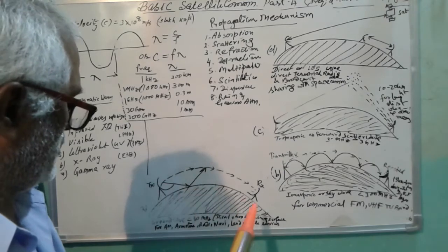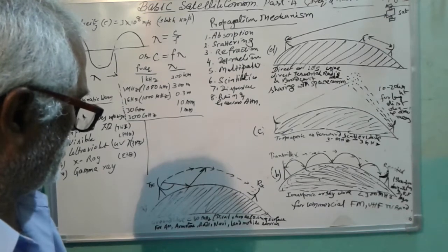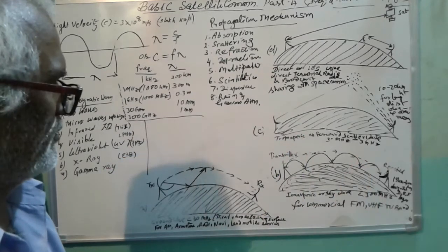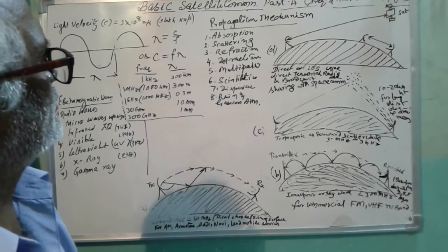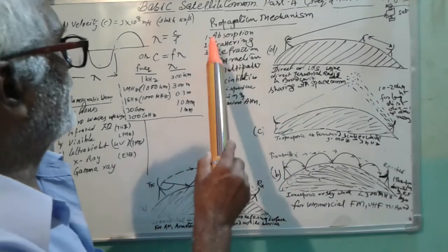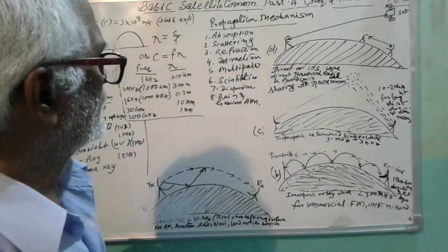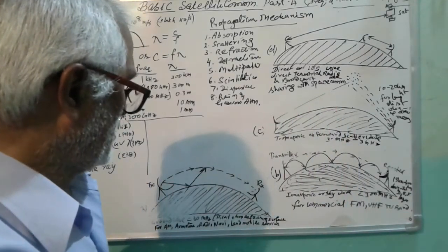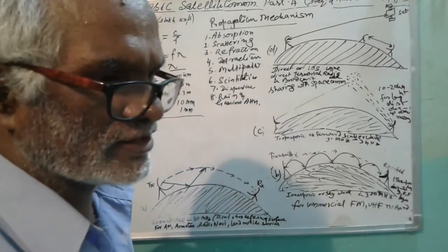In the lowest frequency communication like ground wave, ionospheric, or tropospheric, there are so many propagation mechanisms or propagation phenomena that take place, like absorption, scattering, refraction, diffraction, multipath, scintillation, dispersion. Finally, in high frequency, 10 gigahertz and above, rain attenuation and gaseous attenuation take place.